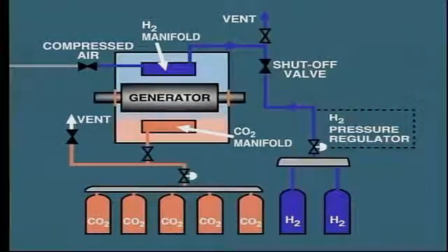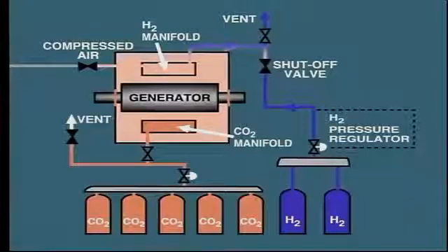The correct valve arrangement must be selected by the operator to allow this top manifold to discharge to atmosphere instead of receiving hydrogen from the bottles. The vent is usually located at a high point of the plant, and there is no danger as the hydrogen is immediately diluted by surrounding atmosphere.